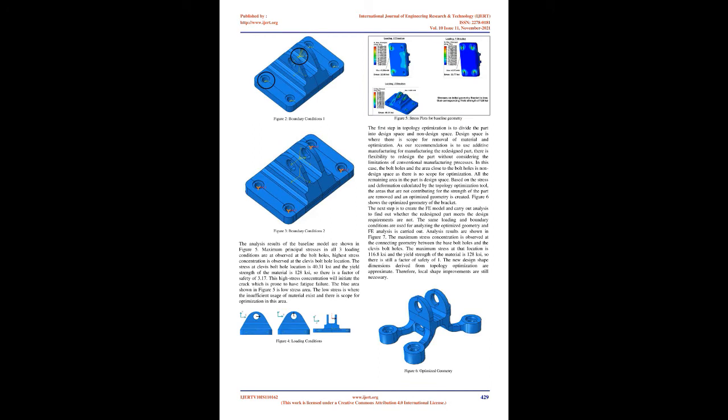The local stiffness tensor E can be formulated by incorporating an integer formulation. V is the volume of the initial design. When the density equals 1 we consider an element to be filled, whereas an element with density equals 0 is considered to be a void element. To use a gradient-based solution strategy, the integer problem needs to be formulated as a continuous function.